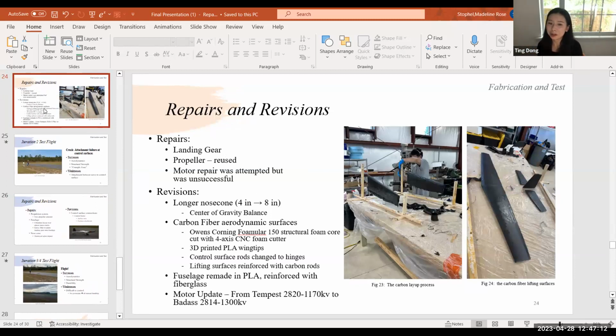I don't know anything about composites, but I'm wondering if using carbon fiber to wrap around the fuselage will interrupt the signal transmission. Yeah, I think so, because carbon fiber is conductive. I was talking to some of the PhDs in my lab, and they strongly encouraged not using carbon fiber for the fuselage and instead using fiberglass, because it is signal transmissive.